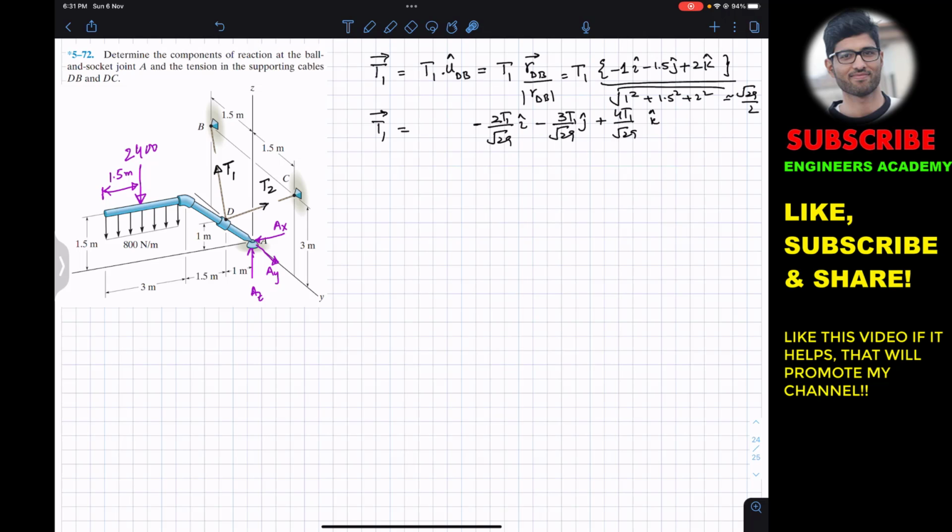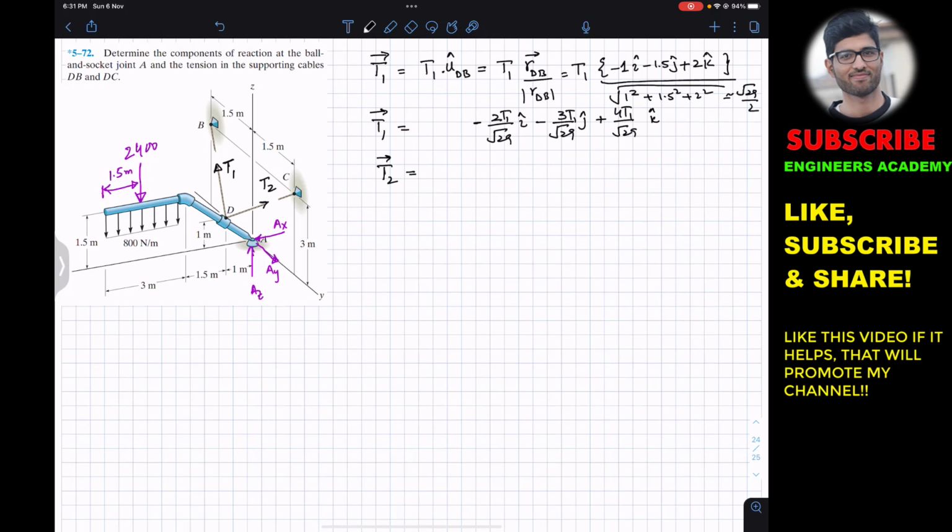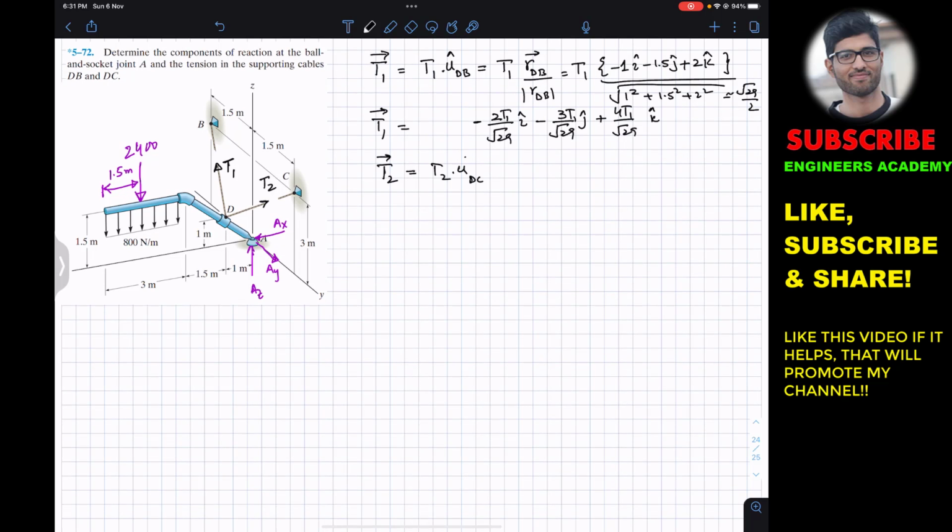Similarly, we have to write this t2 as a Cartesian vector. So for t2, I will write again t2, and then t2 will be equal to t2 times the unit vector. This is t2 magnitude, and the unit vector is from D to C. So this is equal to t2, and again the unit vector from D to C is the position vector from D to C divided by the magnitude of that position vector. So again we will have that same position vector, but instead of minus 1.5 we will have plus 1.5, since this point C is at a distance of 1.5 in the positive y. So everything will remain the same, only this minus 1.5 will become positive.